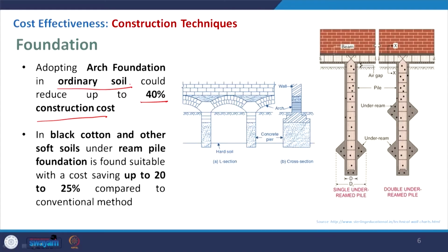We have to remember that we cannot always make similar foundations for all soil conditions. Sometimes you may have a very good bearing capacity of soil. The SBC of soil will determine the type of foundation that we can take. It may be an isolated foundation, a combined foundation, then we can go for the pile foundation and the mat foundation. So, it depends on that.